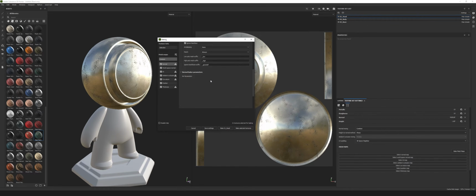But it's important that you do this process, because if you don't, Substance 3D Painter cannot use smart materials, because you need to have those baking maps and that information in order to create those smart materials. So first of all, you can select to bake on all selected texture set lists or just on the head itself, whatever.